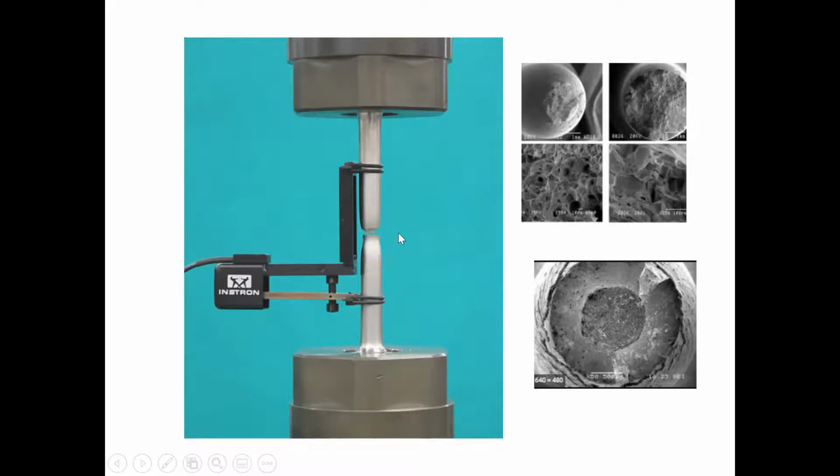And if we take this material and look at it under the electron microscope from the top view, then that's what these are. These are photographs looking down on the fracture surface. If you take these out and put them in the electron microscope afterwards, then it looks like this. Here's the other one. So you can see the thinning down effect. The diameter where it's broken is much thinner than the diameter of the rest of the specimen. And it's more obvious here. You've got different types of fracture here. You can see a different fracture pattern here than you can here. So it's a combination of ductile fracture and brittle fracture, actually.